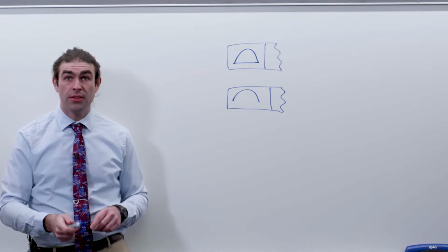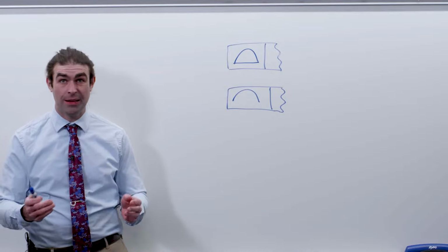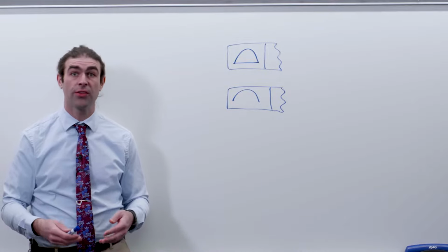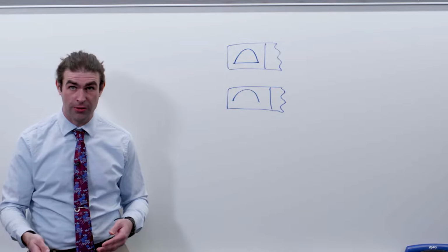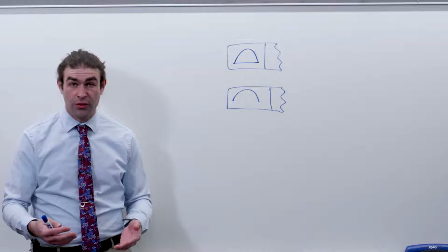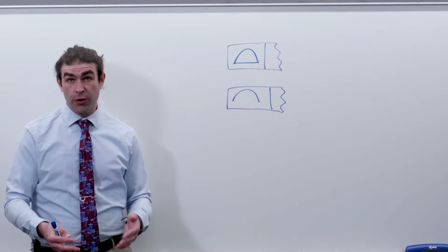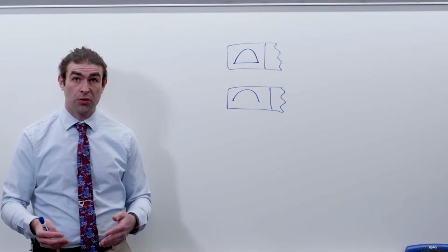The big difference, and I'll explain more about this in a minute, is that profile is not limited to flat surfaces like flatness and things like parallelism are. Profile can be used for curved surfaces, surfaces of revolutions, and flat surfaces. So it's a very versatile geometric characteristic.